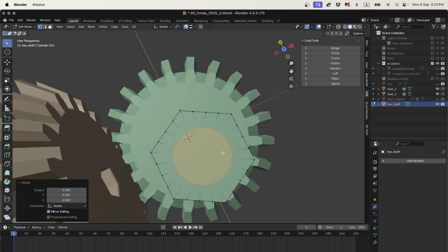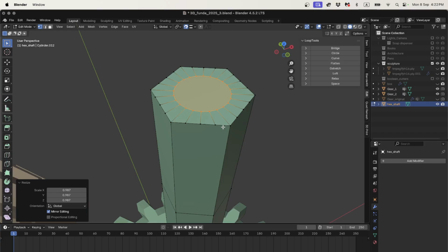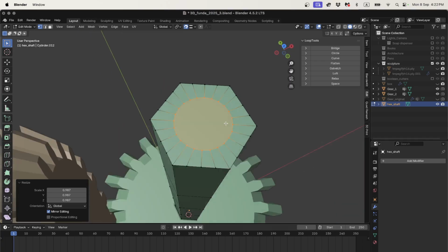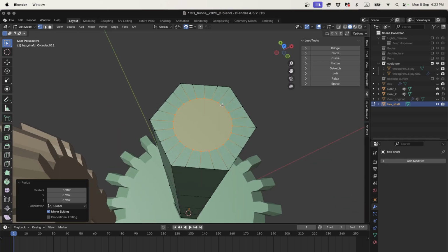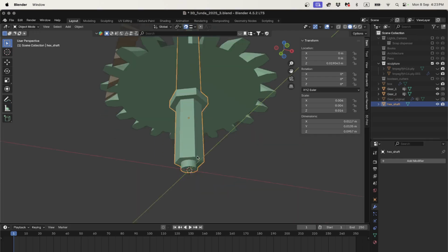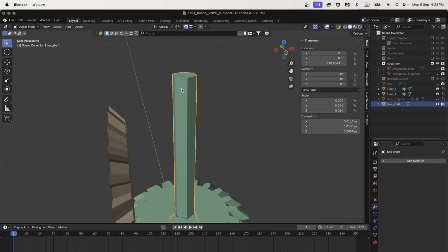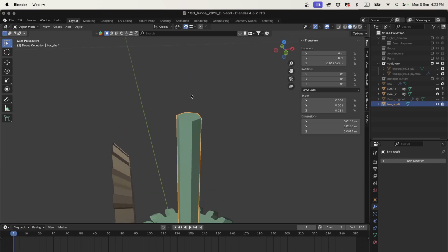But before I do that, we're going to change this from being a circle to what we call a D shaft or a D socket. In this case, it's going to be a circle with a straight line going across it. The reason for that is that our circle down here, we want that to spin without rotating the box. But up here, we want this to spin and rotate whatever's on top of it.